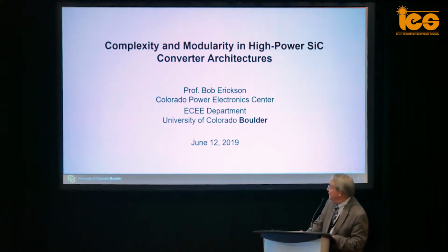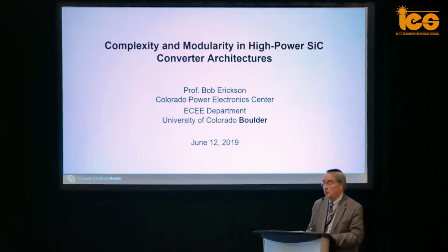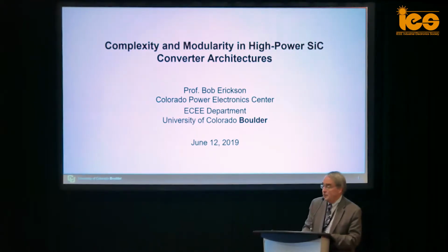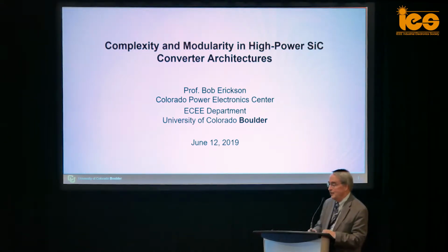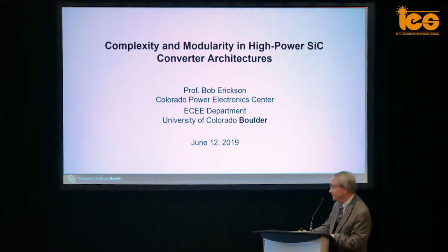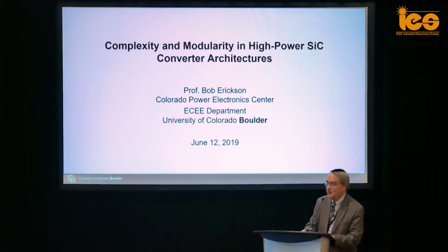So the interesting thing today is that we have these silicon carbide devices that can switch very fast at much higher voltages and power levels than we've been able to do in the past. And this really opens opportunities for new applications at much higher voltage and power levels. So one way to build a higher power, higher voltage converter, say a bigger boost converter, is to buy two big transistors and a bigger inductor and some bigger capacitors and connect them in the old way. And that's probably the normal way to do it.